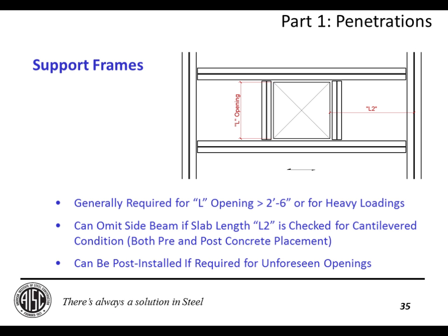There comes a time when the opening is large enough or there's heavy enough loading that you need an actual steel support frame. In this instance, I normally do about 2'6" or 3 foot as the maximum opening I would really think is a good idea in a composite slab.